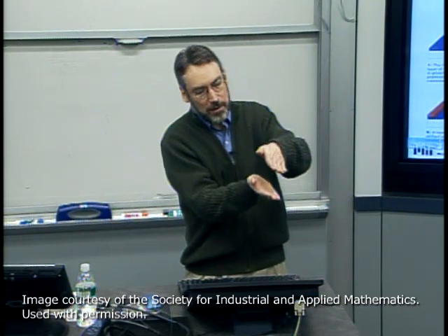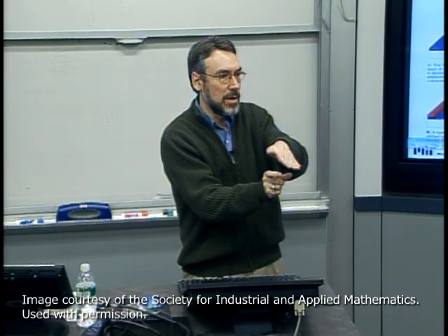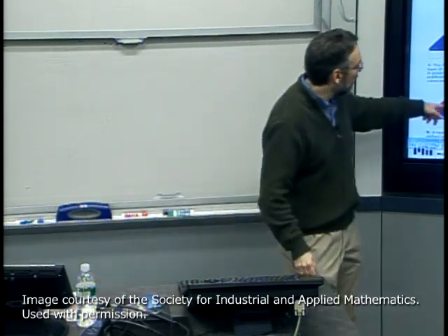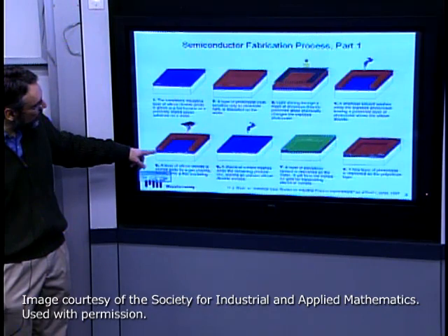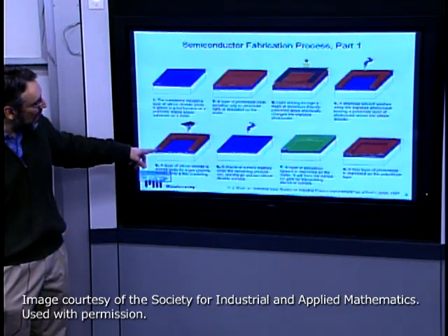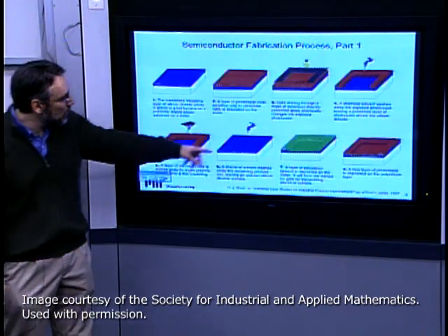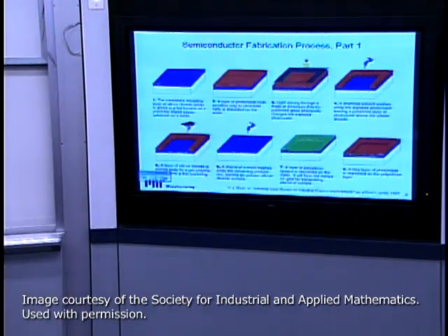And the reason is, the closer I can get my 2 plates of that capacitor, the more capacitance I have, and the more control I have of the silicon surface. Okay, so the harder I can turn the device on, the more current I can flow per unit area, and so on. Okay, so in this process, apparently we're etching from about a half micron, 5,000 angstroms, down to, we might be at 100 angstrom or below remaining gate oxide layer, which in a modern process is really what you want.